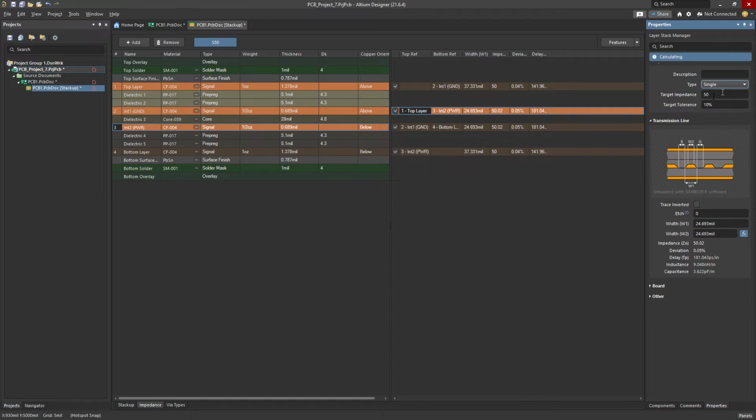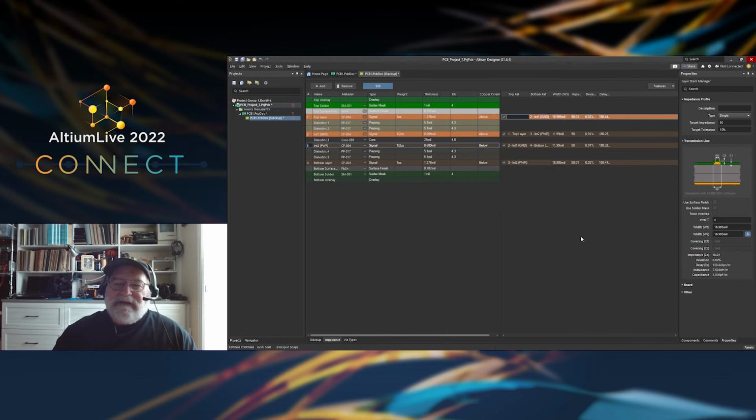So we're going to take a quick look at microstrip transmission line, and then we'll go to a strip line transmission line. So let's go back to our microstrip, and here's what we're going to do. We know how to access it. We know how to set it up. Let's do a simple estimate for analysis. In other words, we're going to put the geometry information in. We're going to calculate what's the characteristic impedance.